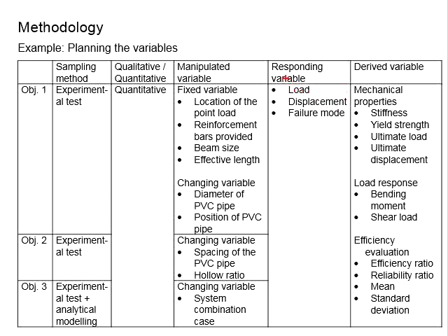Let's say now you have acquired the load data and displacement data as well as the failure mode. You know that if you find the relationship between the load and displacement over the time, you will acquire a load displacement curve. And this load displacement curve, through a processing process, you are able to find the gradient, find the turning points, find the highest point, and so on and so forth, for you to acquire the mechanical properties of the specimens.